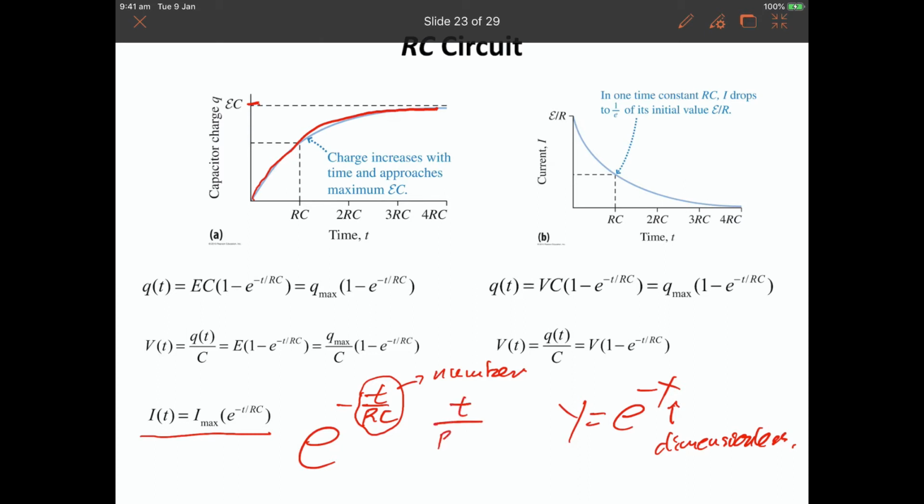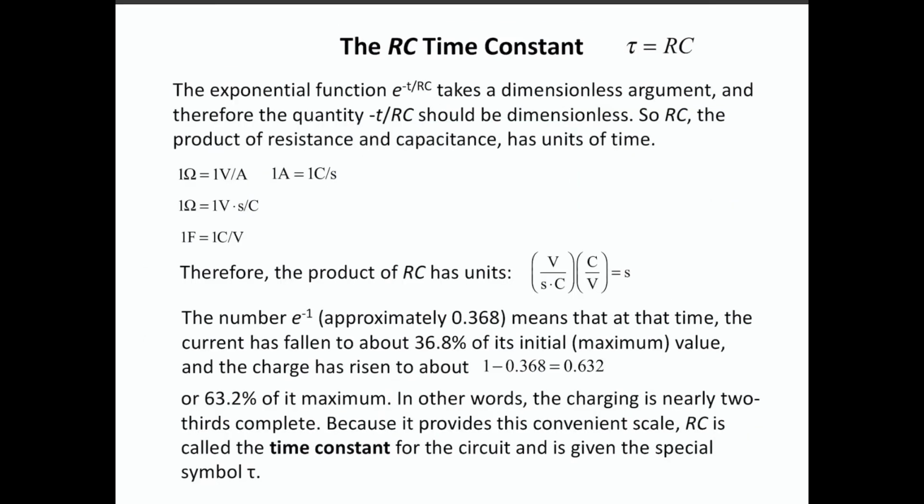What is the unit of T? Second. So what is the unit of RC? It has to be second. It doesn't look like it is second. Therefore we first prove this property here. RC, I want to prove, is second, is a time.